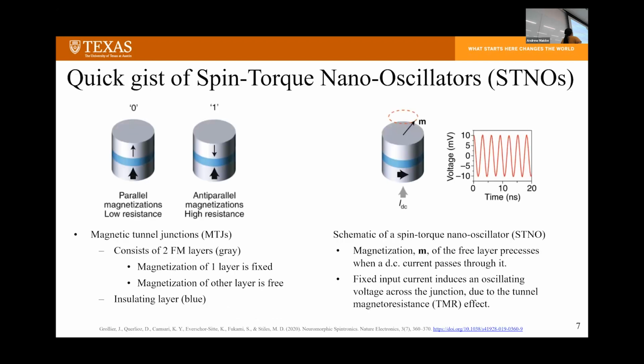So for the remainder of the slides, I'll call spin torque nano oscillators STNOs. STNOs are a type of magnetic tunnel junction, which can serve as synapses and neurons, the basic blocks of the neural network of the brain. Now, MTJs are of particular interest in neuromorphic computing systems because they're compatible with standard integrated circuits, as well as can support multiple functionalities such as high scalability, high speed voltage operation, as well as non-volatile memory.